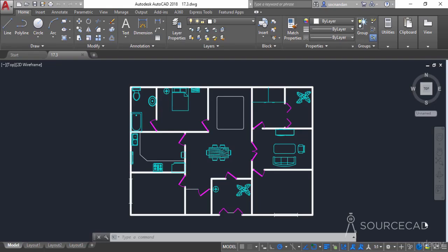In this video, I will tell you about the Design Center tool of AutoCAD. So Design Center is a single utility which can be used to access named components within a drawing. For example, using Design Center, you can extract layers, blocks, line types, and other information from a drawing without directly importing the complete drawing.